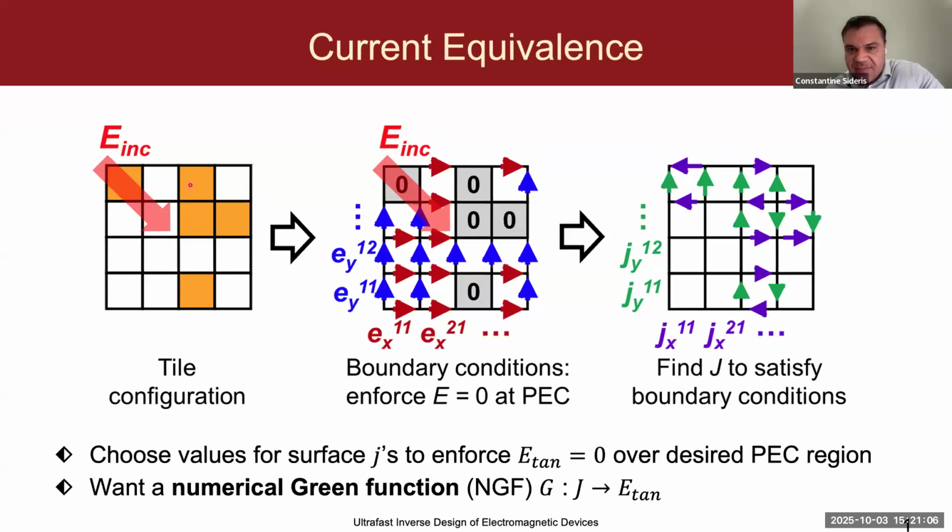So what we're effectively doing here is using a numerical Green's function for the optimization domain. And because it's a numerical Green's function, and we're using an electromagnetic solver to compute that, it means that the surrounding environment can be anything. It's not limited to open free space. It's not limited to layered substrates. It could be finite circuit boards. It could be different chips. It could be chips on circuit boards. The limits are essentially just your computational power available and the bounds of your imagination.